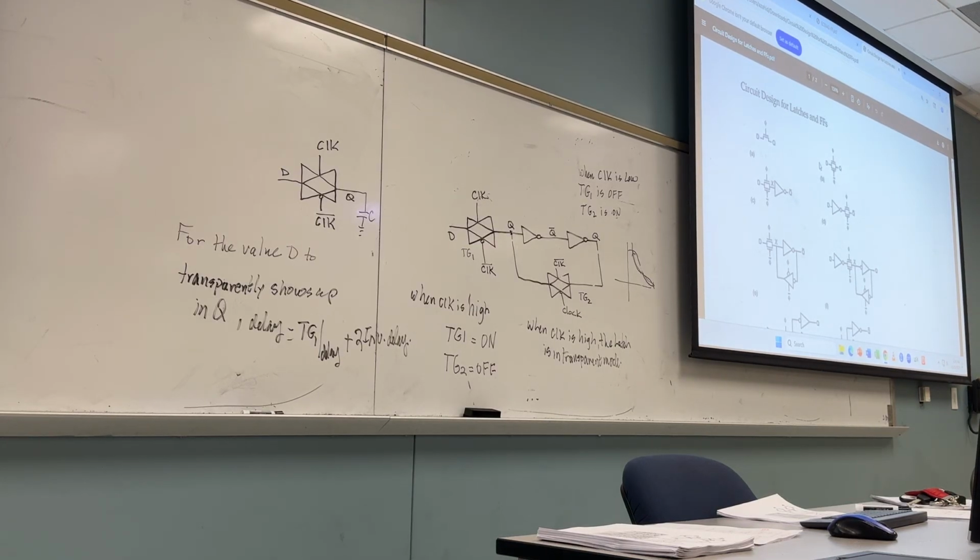Okay. Can we try it one more time? What does the propagation delay depend on? Do you remember the equation of TP? Yes? What was in the denominator? W over what? L. L in the denominator, which means what? If you make the W over L higher, the delay becomes what? Lower. Do you follow me or not? Yes.